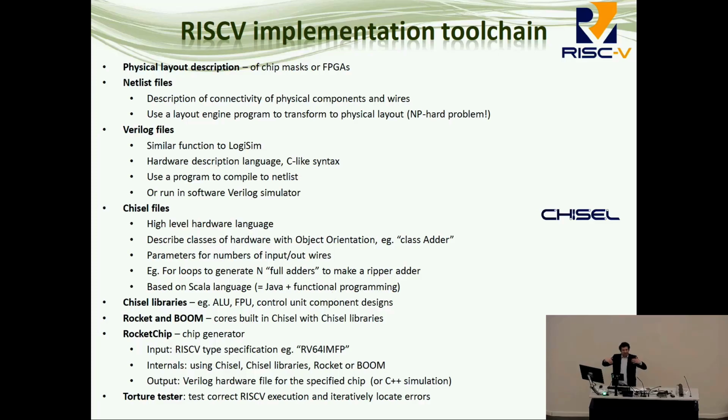So when I was a student, Verilog was the highest level you could go, and it was still, compared to an object-oriented language like Java or Python, very low level. You were still dealing with wires and adders. What we have now from the RISC-V community is this very high-level tool called Chisel. You can see Chisel's logo uses the same font as RISC-V. It's developed as a separate project, but they're very closely linked. And it's the main tool used to develop RISC-V. And Chisel, for the first time, gives us a real modern high-level language for doing hardware design. It looks a lot like Scala, which in turn looks rather like Java, plus some ideas from the Lambda calculus and from functional programming. So it's kind of a weird mix of low-level hardware work and very high-level language abstractions.